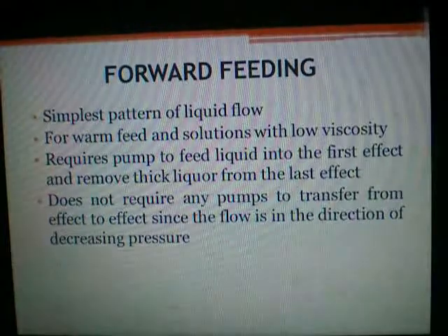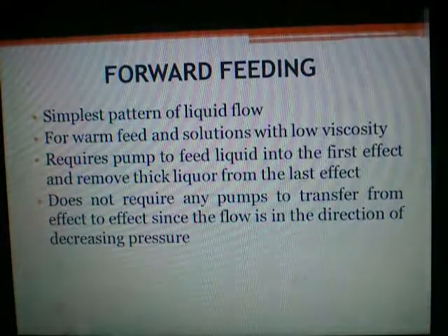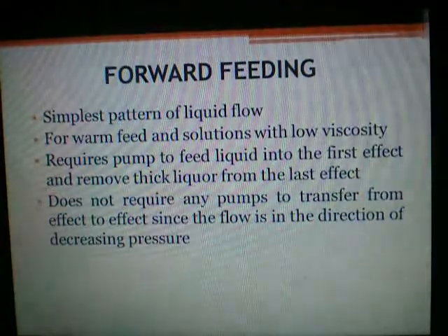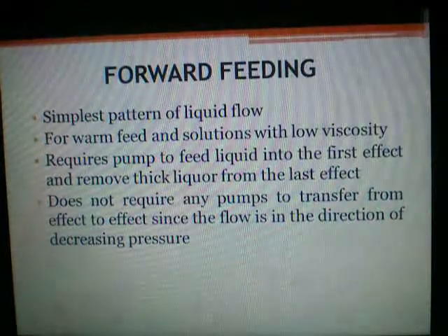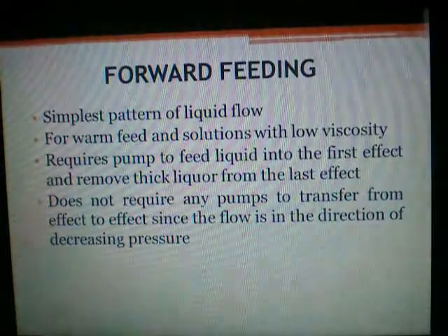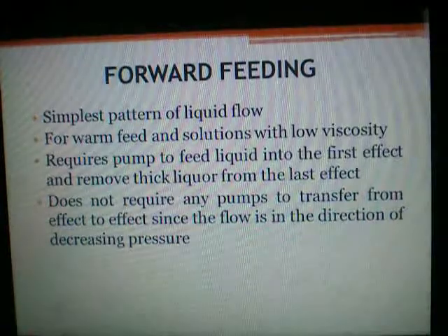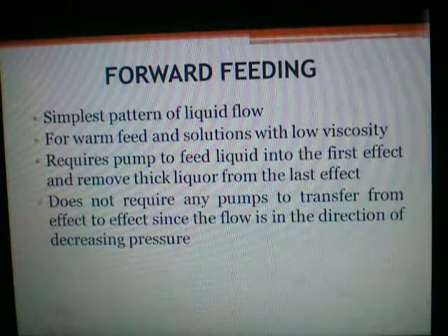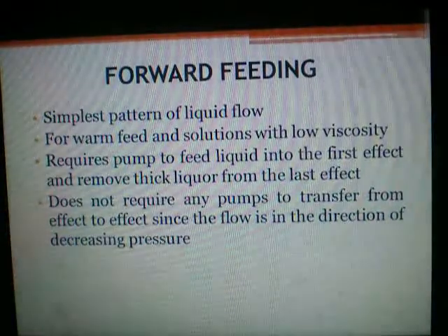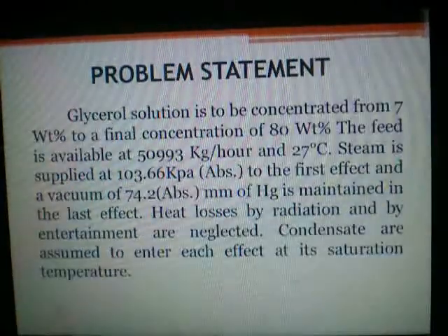Forward feeding is the type or method of feeding that is suitable for warm feed and solutions with low viscosity. It will not require any pump to transfer from effect to effect, but will require one to feed liquid into the first effect and remove thick liquor from the last.